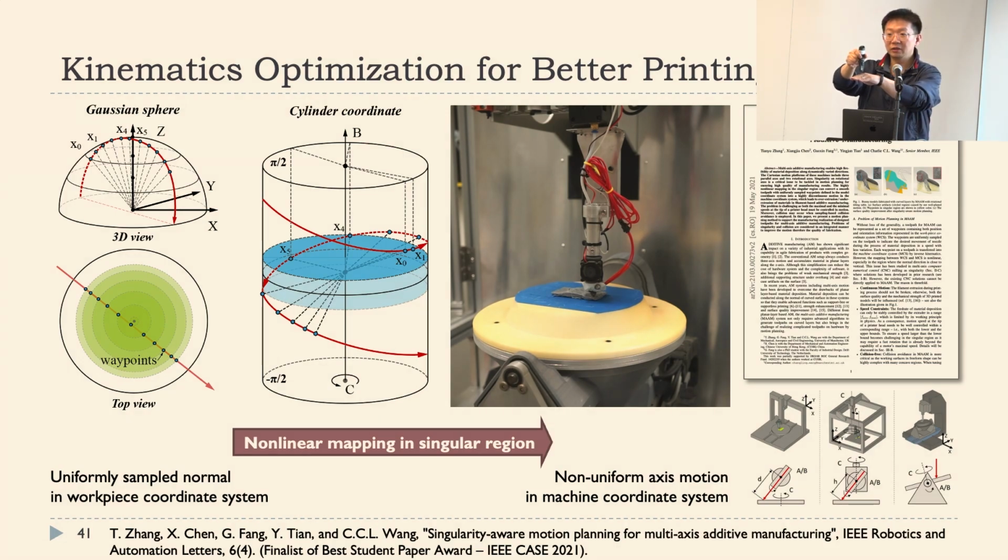But how this is realized on the hardware of the machine is that you need to have this plate, which is called the c-axis, rotate a little bit, right? Very fast. So it turns out, to have a slightly tilted orientation, you need a superpower motor, which allows the c-axis to rotate very fast, which is hard to realize. So this is called machine singularity inside of the domain.